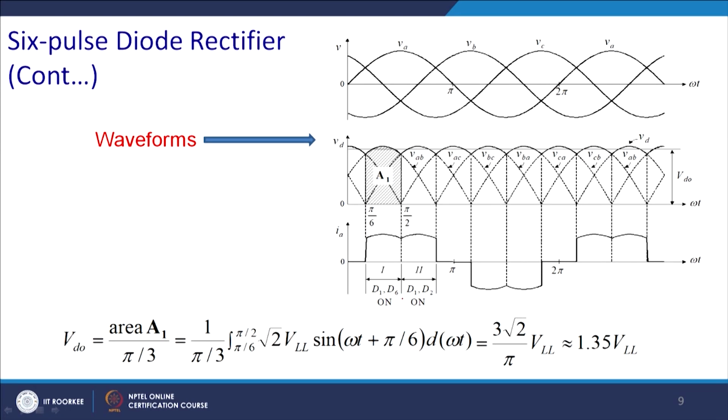That will come later, but let us talk about this 6 pulse diode bridge rectifier, and ultimately what you get is the VAB, and that is the simplest circuit we can have in 3 phase, and this one is root 3 VL sin(omega t minus pi by 6). Similarly, we can calculate the current pattern: instead of the square wave we will have this kind of waveform for a resistive load, but if you make the load RL, you can get a straight line for the inductive load.